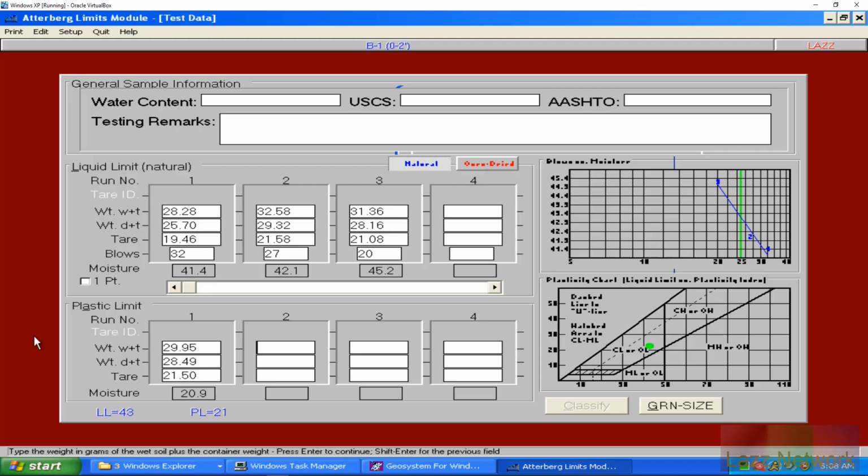So it's only been a few years ago that the spec has changed, that it says you were to grab a 10-gram sample instead of an 8-gram sample. But where things get conflicting is it says you're going to use 4 tears, but you're still going to do 1.5 to 2-gram samples. So then technically by the end, you're going to have a 1.5 to 2-gram ball out of the 4 samples.